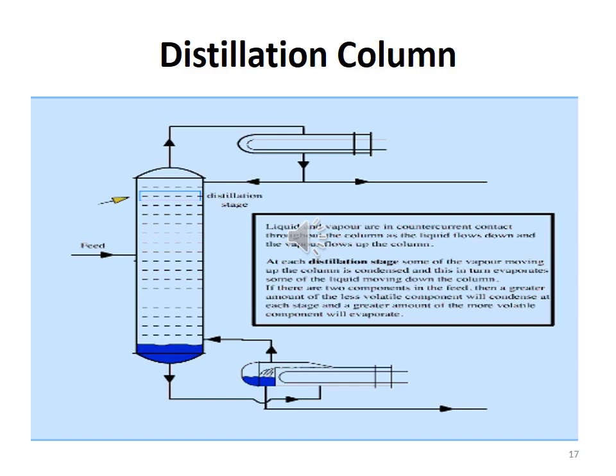So when the mixture containing different components is introduced in the distillation column, there are basically two phases. One is the liquid state and the other is the vapors, which got a small amount of energy from the reboiler. When these liquid and vapors interact, some of the molecules which have lower volatility will condense and fall back, moving down the column with the liquid.